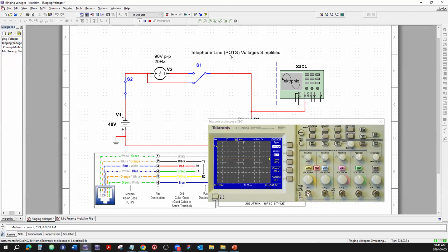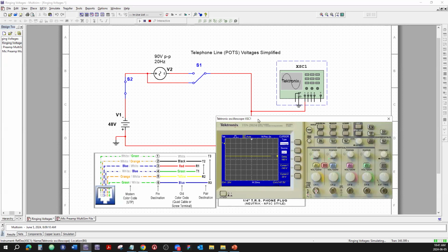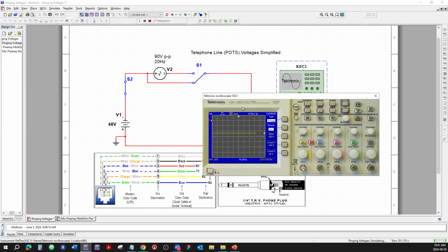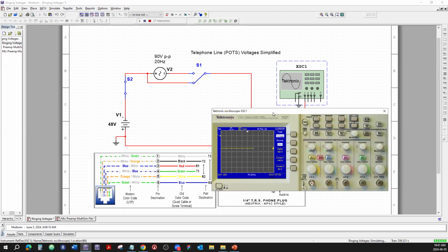All right, now those paging interfaces work on POTS, plain old telephone service signal. They understand the POTS. So in order to activate a paging interface, you need to produce a ringing signal for that thing to automatically respond and react whichever way you program it to react. So the paging interface is looking for that. There are different brands, and we'll talk about that when we get to it. For example, if there's a VoIP telephone system, it doesn't connect into any box that's sitting or hanging on the wall, although it can be, and we'll talk about that too. But it's all Ethernet signal.